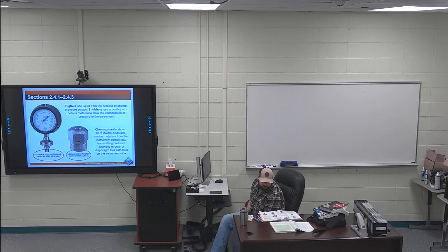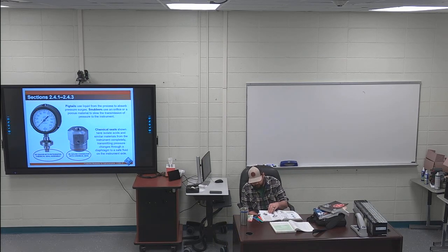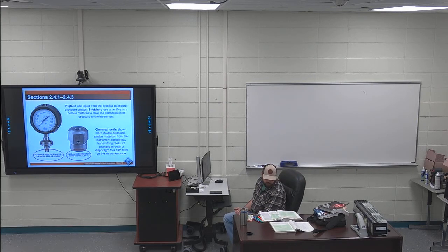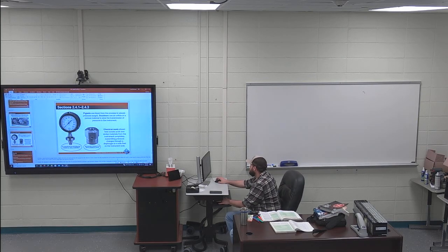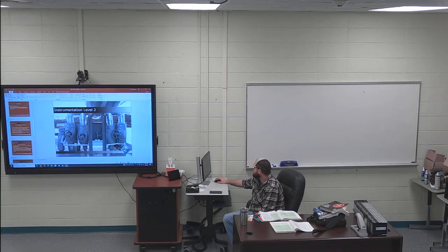Skip a paragraph, and I've got the next paragraph, the whole thing highlighted, online test question. If workers are welding or using torches or grinders in the area where instrumentation is installed, they must use protective blankets to prevent weld splatter or other debris from damaging instrumentation components. Keep pieces of instrumentation out of welded areas. So you've got section 2 review on page 28. I'm going to continue on and finish out with section 3.